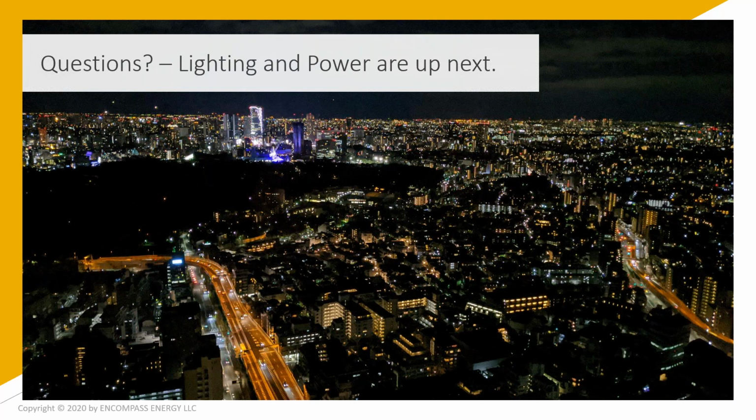But for normal sized dwelling units, say up to 500 or 600 square feet, you're going to have one zone per unit. If you're getting to very large ones, like these apartments in New York that are 10,000 square feet, you might have multiple zones, but generally for a multifamily building, you're going to have one zone per dwelling unit.